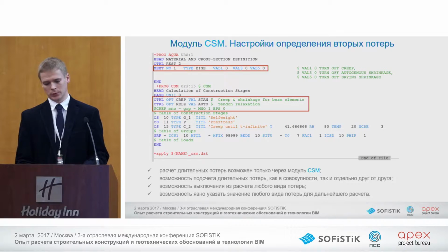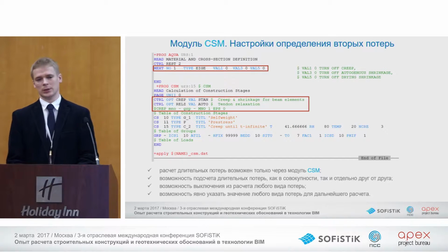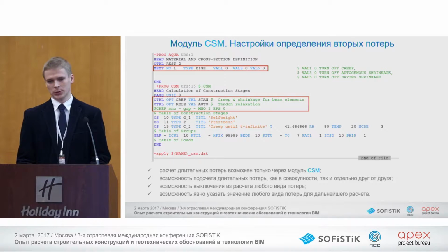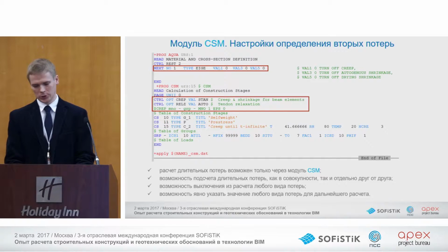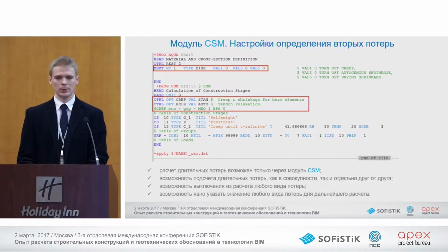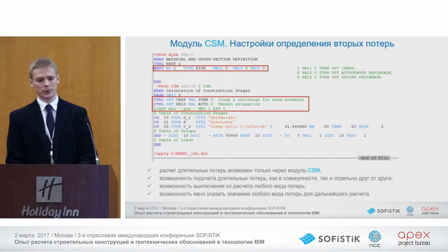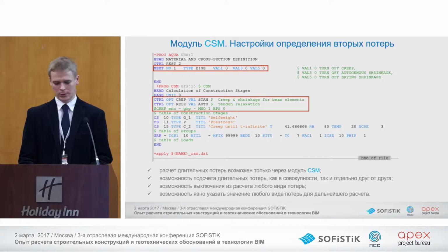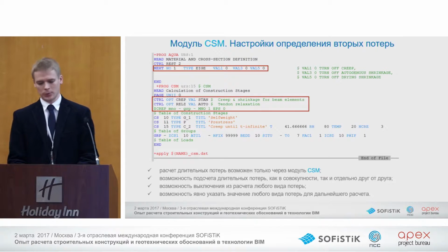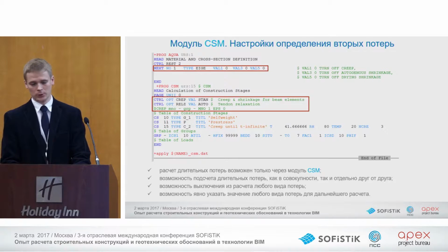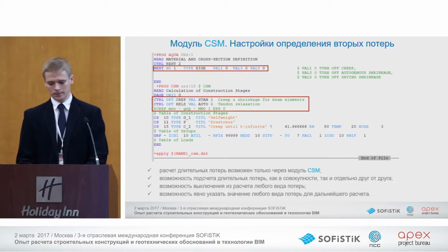And this CSM module is very crucial. If you use this module, you can calculate the difference between pre-tensioning and post-tensioning. And so construction stage sequence is very important, and time effects. Secondary hyperstatic, second-order parasitic effects, you can take them into account. It's a very accurate calculation, and I would like to thank the developers because it saves a lot of time for engineers.